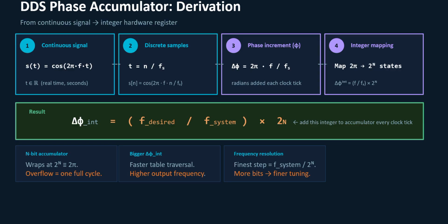Inside the DDS there is also an accumulator, so it accumulates. The first sample is the first phase increment, the second time the phase increment multiplied by 2, then multiplied by 3, and so on. At the same time, there is a lookup table that generates an amplitude corresponding to each phase output.